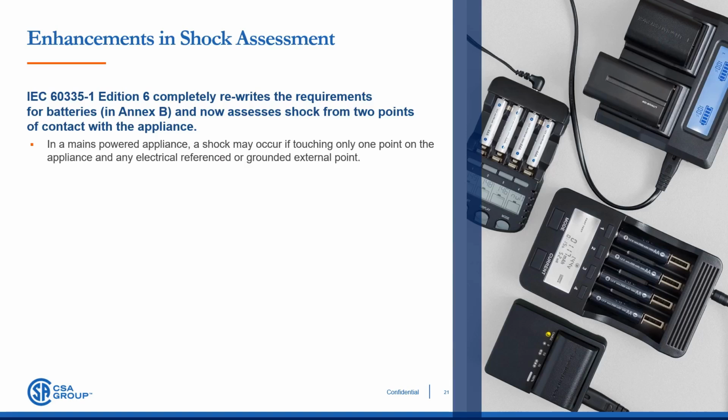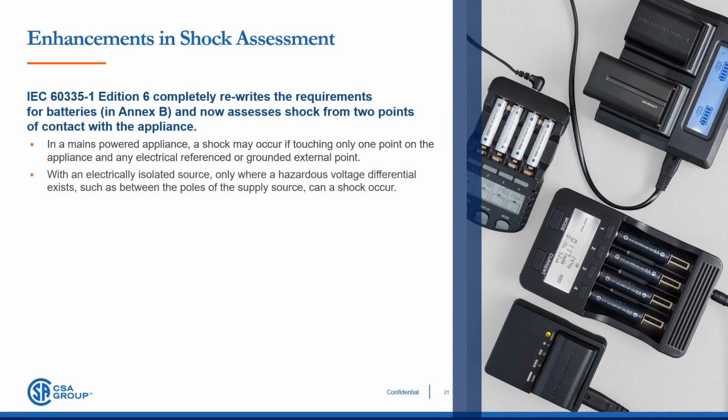However, when a current carrying point is electrically isolated and decoupled from any other voltage reference, then even under a fault condition, touching any single point of the circuit cannot result in a shock. In situations where an adequately isolated electrical source at any voltage is touched, the opposite supply output from the isolation transformer or DC terminal will simply drift to the potential difference in voltage without causing any harm, even if an external grounded point is contacted.